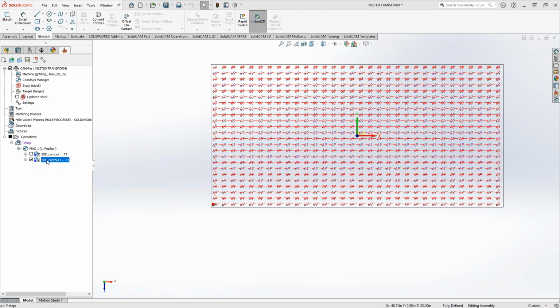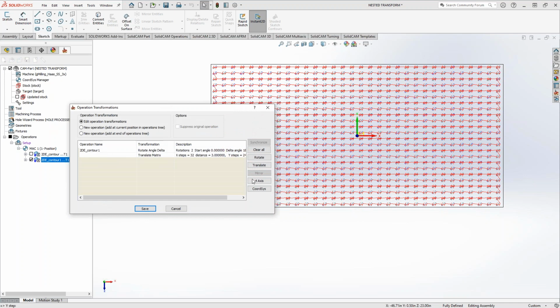Yeah, absolutely. And if we go back to the transform command, that's very useful for that last option there, coordinate system, where let's say on one table of your machine, you've got 4 different parts. And this being a Haas, it would be G54, G55, G56, G57. Wherever they are on the table, they don't even have to be in a properly set up array or anything like that. They just have to be set up by offsets. I can transform any toolpath from one coordinate system to another.